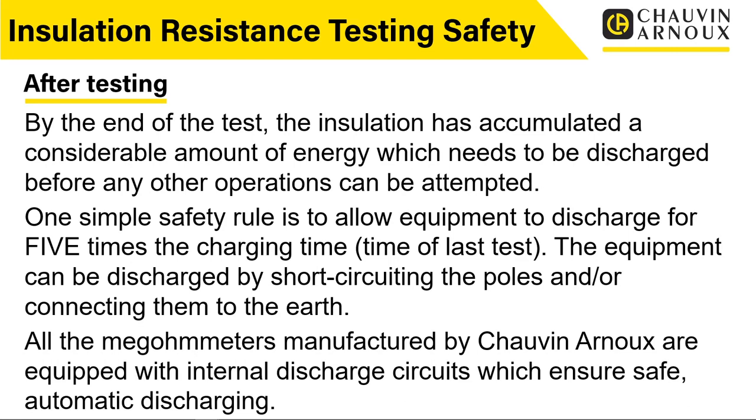So again, think about that. If you are moving from point to point, you may need to manually discharge them or use a test lead or something to discharge those parts after the test. Also, it's important to leave the tester connected for a period of time after you've stopped the test to allow that discharge to take place. So just be aware of those things. It's an important safety precaution, often gets missed.